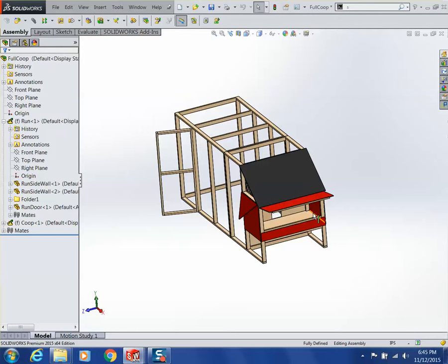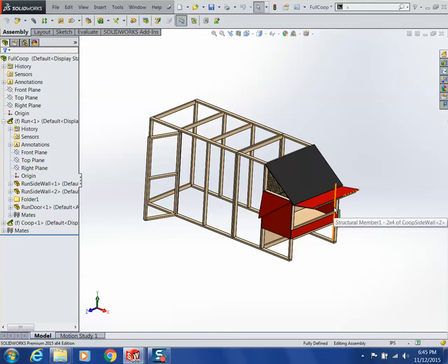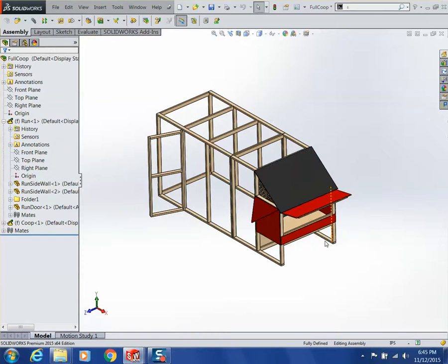If you've got a couple different parts that have to be tied specifically to the size of another thing, you can start to do that. But having a raw part to start with, that's the rough size and shape you need, is going to save you a lot of time and a little bit of sanity if you have to make changes later. So whenever you can, if I'm going to need a plate, well, let's go make a plate first. It doesn't really matter what size, but let's get one and bring it in and work from that direction.